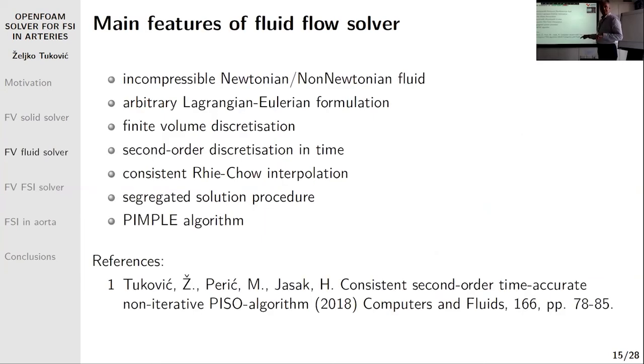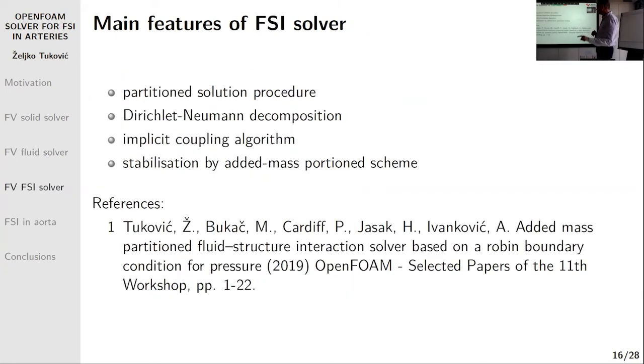Fluid solver is standard, based on arbitrary Lagrangian-Eulerian formulation. You can use Newtonian and non-Newtonian fluids. PIMPLE algorithm is used for the solution procedure and so on. So main features of FSI solver: partitioned solution procedure is used, Dirichlet-Neumann decomposition, implicit coupling algorithm, iterative solution procedure, and stabilization is done by added mass partitioned scheme.